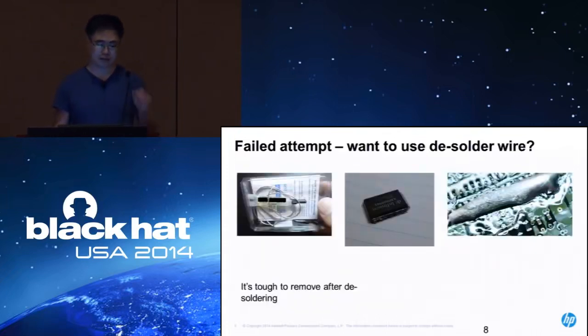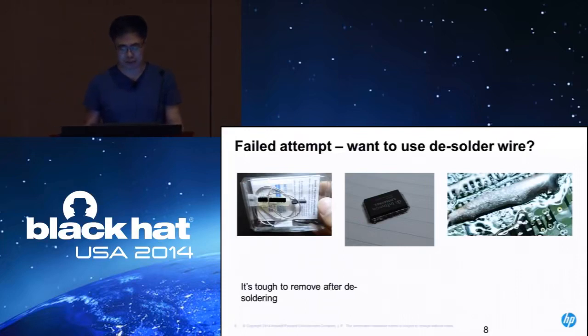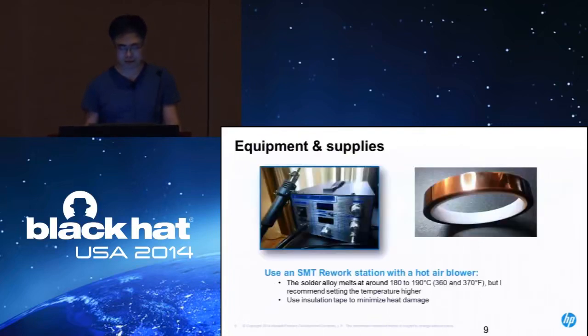The other option is desoldering the chip using ChipQuick. I tried this on other types of chips, but it makes the chips really messy, and the PCB board is filled with the remaining solder fluid. I didn't like this option, though other people use it a lot, I guess.